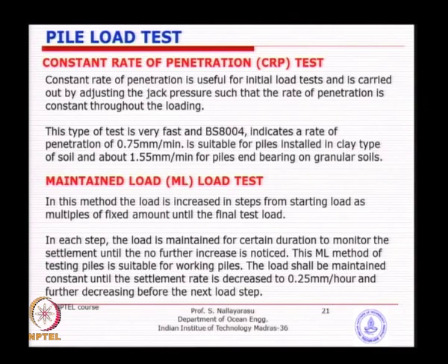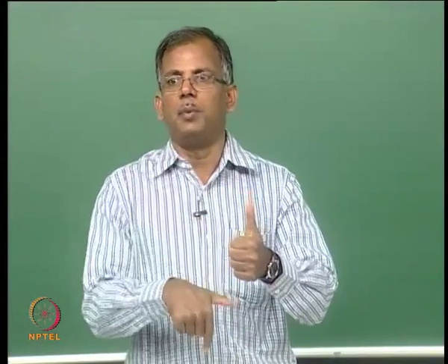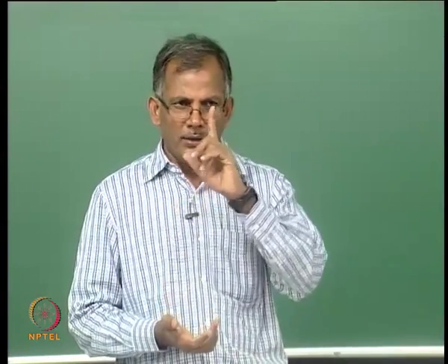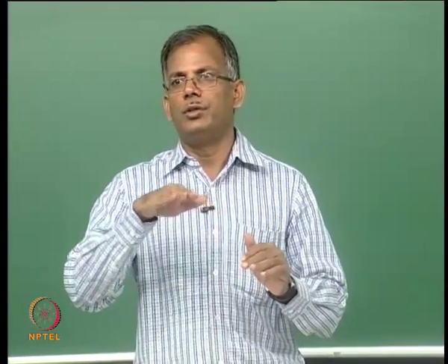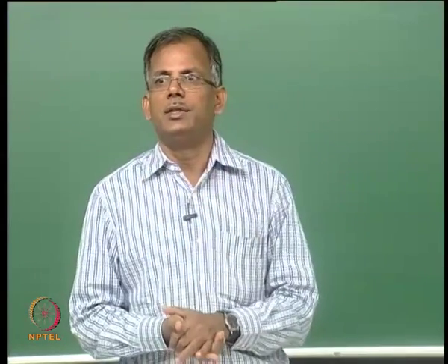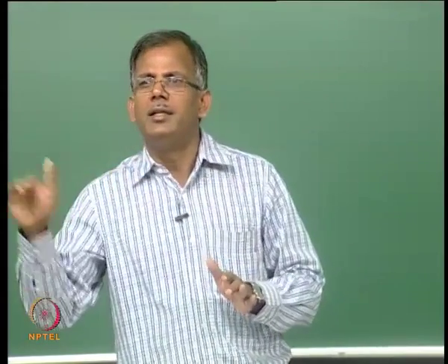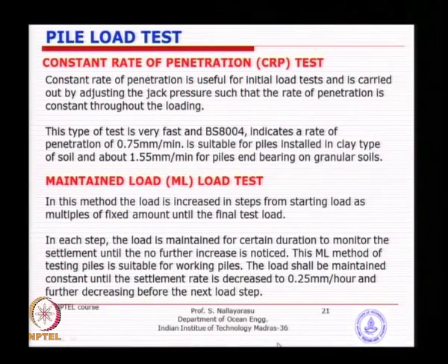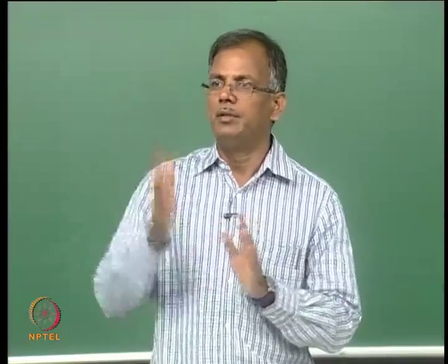So, in step 1, put the load and activate the hydraulic jack to transfer the load to the test pile, relieving the anchorage piles or support system, and then monitor the displacement. Initially the displacement of the pile may be larger, slowly reducing, indicating that the soil has reached its failure state at that load, and then it will go constant or increase by a very low increment. Once you see the displacement graph becomes flat, you are not expecting any more immediate settlement. You may expect long term settlement, which may take several years, but we are not interested in that.